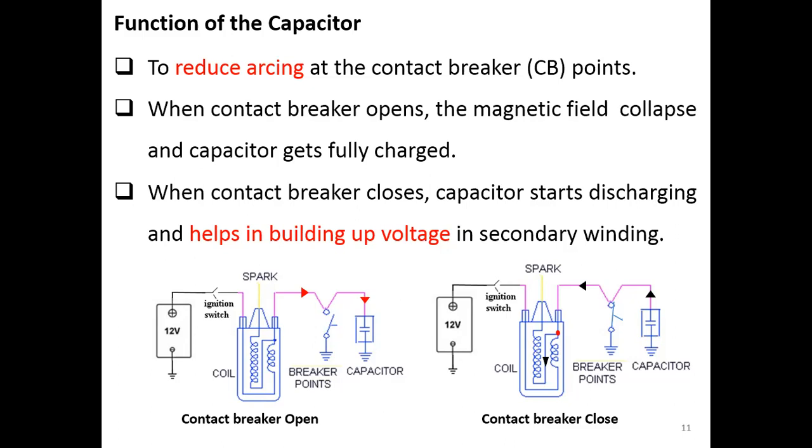And then this voltage will go to the distributor rotor. The distributor rotor has a rotor that will make contact with the contact points. When it makes contact with one of the contact points, it will send the high current, due to the high voltage, to the spark plug, so that the electricity can jump over the gap and create the combustion in the cylinders.